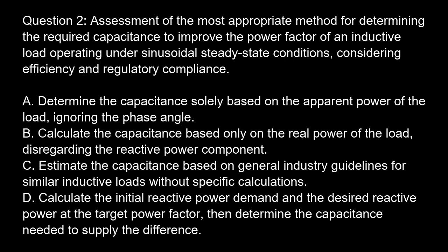Option A. Determine the capacitance solely based on the apparent power of the load, ignoring the phase angle. Option B. Calculate the capacitance based only on the real power of the load, disregarding the reactive power component. Option C. Estimate the capacitance based on general industry guidelines for similar inductive loads without specific calculations. Option D. Calculate the initial reactive power demand and the desired reactive power at the target power factor, then determine the capacitance needed to supply the difference.